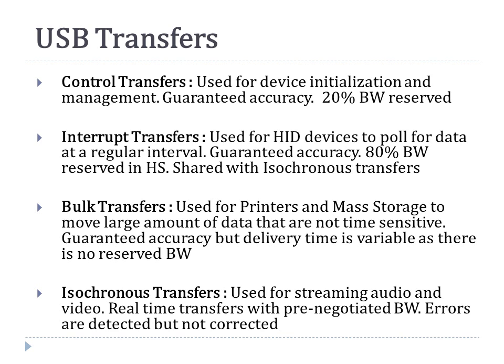A very important kind of transfer is interrupt transfers, and this is basically used for HID devices to poll for data at regular intervals. Let me try to give an example where the interrupt transfers are used. Say you are using a mouse. So how it works is the USB host polls for the data from the mouse at regular intervals. It's actually 8 milliseconds, and the device driver and the software at the host, once it reads the data from the mouse, does the required functionality of moving the pointer on the screen.